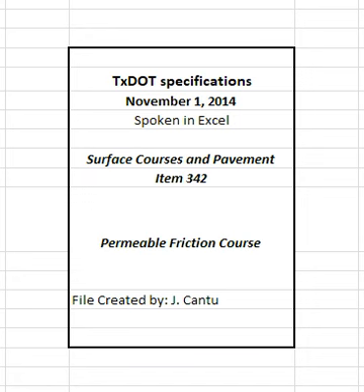2.1 Aggregate. Furnish aggregates from sources that conform to the requirements shown in Table 1 and as specified in this section. Aggregate requirements in this section, including those shown in Table 1, may be modified or eliminated when shown on the plans. Additional aggregate requirements may be specified when shown on the plans. Provide aggregate stockpiles that meet the definitions in this section for coarse aggregate. Do not use intermediate or fine aggregate in permeable friction course, PFC, mixtures. Aggregate from reclaimed asphalt pavement, RAP, is not required to meet Table 1 requirements unless otherwise shown on the plans.